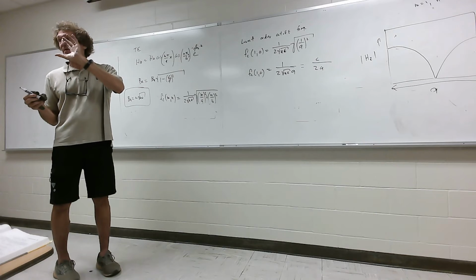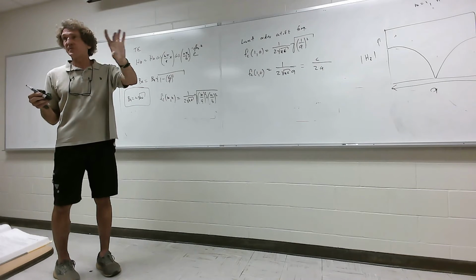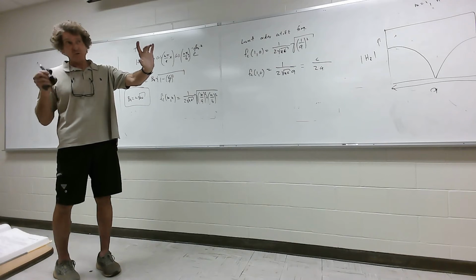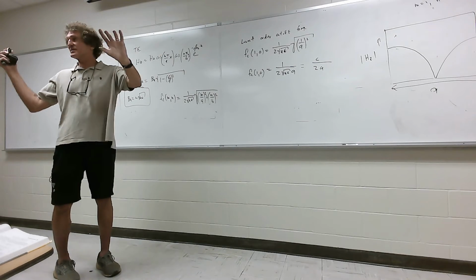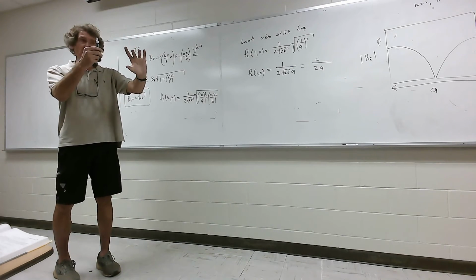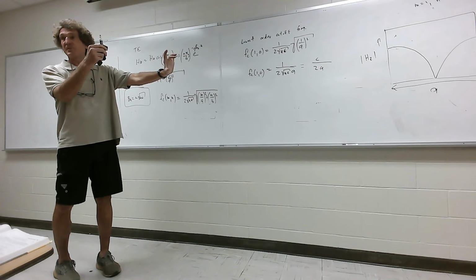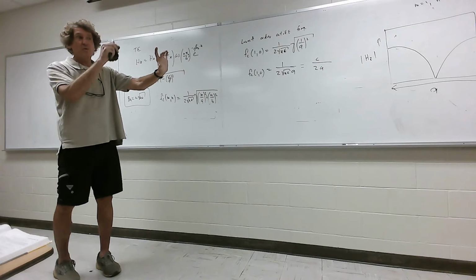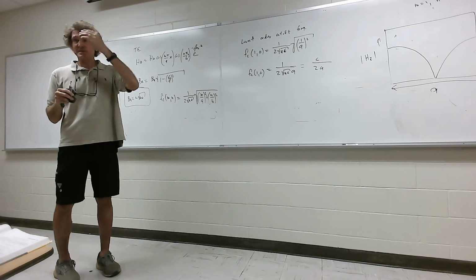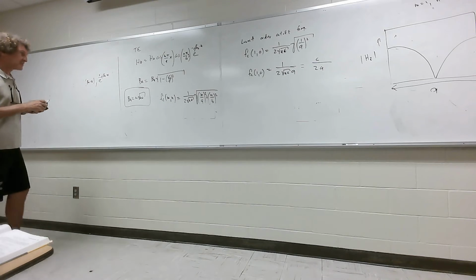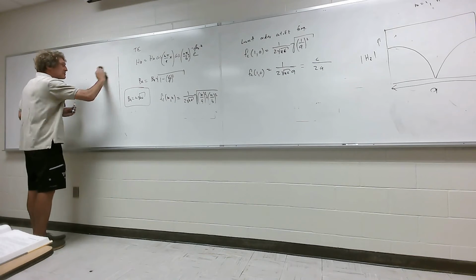They have a design filter that will bleed off the 2-0 mode, so only the 1-0 mode will propagate. But they can send 2 modes down the same guide, same piping. Then they bleed off the 2-0 mode if they need it for something, and the 1-0 mode will be left, if they can do it. But this is a lot more trouble than it's worth, in my opinion. It's better to have 2 guides, just run them in parallel.